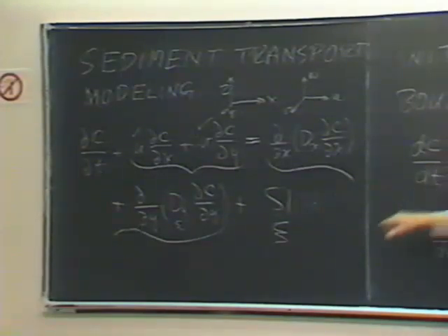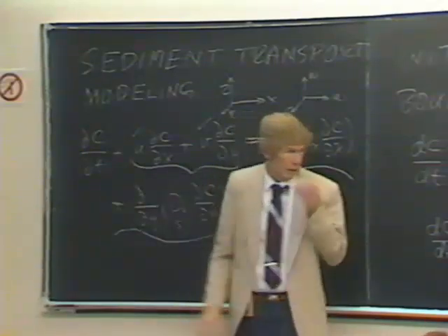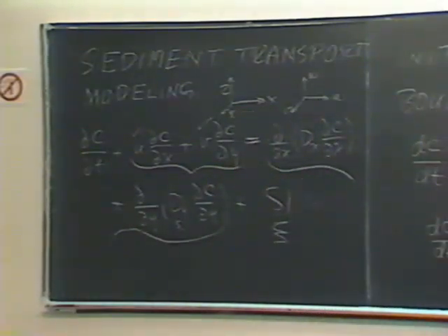Okay, and that's a tough problem. In even that simple system, knowing the suspended solids concentration throughout the modeling time is just about impossible. I've taken 2 approaches to that, and I think there are 3, but 2 that I recommend. One, if you have data on the harbor before it's modified, say you just want to modify a harbor, it changes an entrance or something, then what you do is adjust the concentration at the entrance to some representative concentration that gives you the observed rate of deposition.